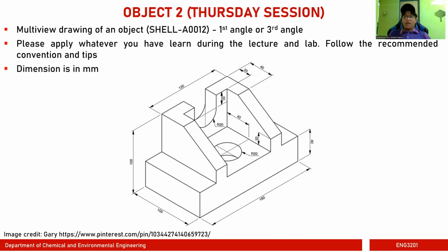Again, because this is a 2D drawing, I do expect you guys to draw fairly quickly because it's just a simple drawing that we have learned before. It's going to be a simple use of lines, circles, join, trim, copy, move, and so on and so forth. Again, I recommend you follow the convention and the tips that I have highlighted during the class session. In this case, the dimension is in millimeters.